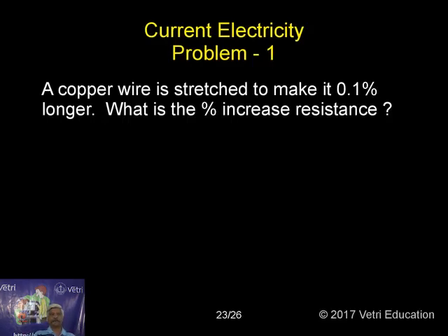In an ohmic circuit, we are getting a linear curve, a straight line. Kindly recollect our previous classes. In a non-ohmic circuit, there is a curvature, as in a semiconductor and a transistor. They won't follow Ohm's law. There the resistance is called dynamic resistance, here ohmic resistance. R is equal to V by I, and dynamic is delta V by delta I. So what is specific resistance?